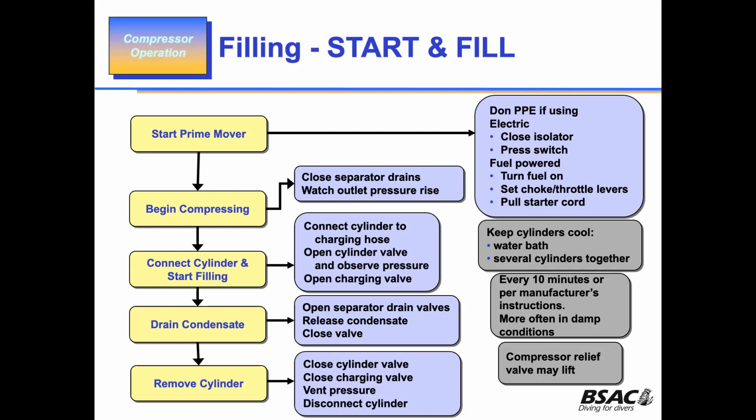If you don't do it in a certain sequence, or if you're too slow, you may get this horrible whoosh, which will scare the living daylights out of you. But don't worry about it. What's happened is the compressor is protecting itself because the relief valve is lifted. And it's quite frightening, especially on a big complex where you've got a lot of banks, right? And a nice big compressor. And you think, oh my God, what have I done? You haven't done anything. The compressor's looking after itself, all right? So it just relieves that pressure.